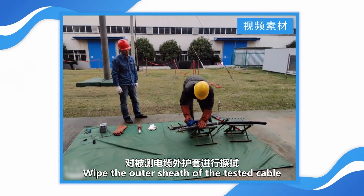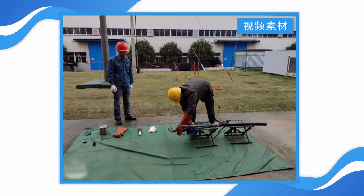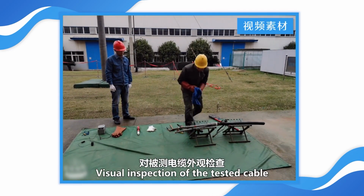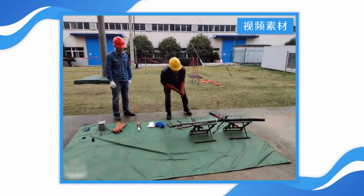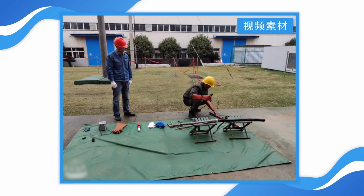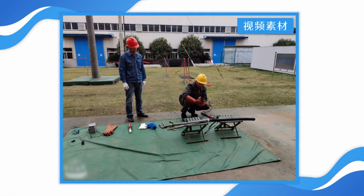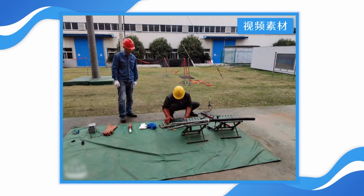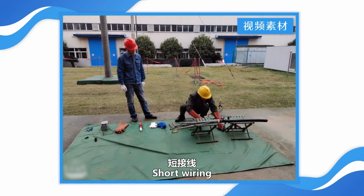Wipe the outer sheath of the tested cable. Visual inspection of the tested cable: no cracks, no bending. Connect the grounding wire. Connect the short-circuit wires.